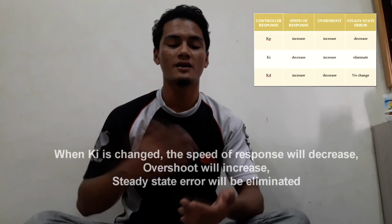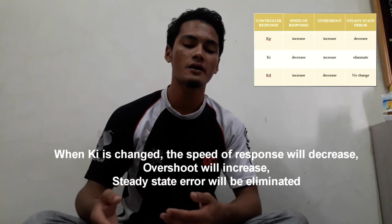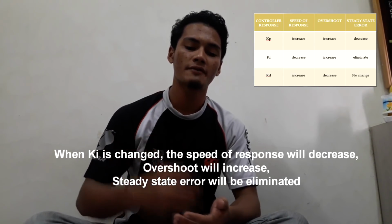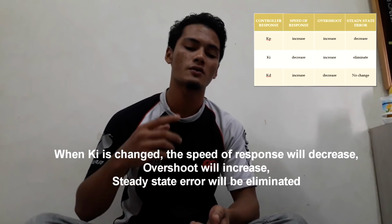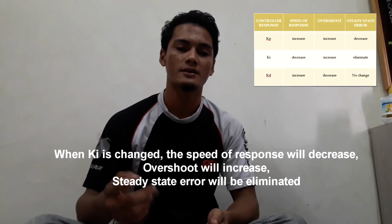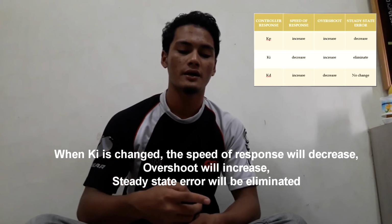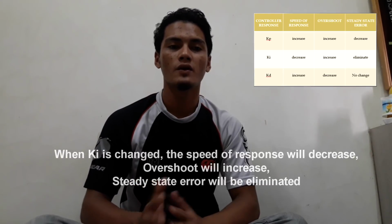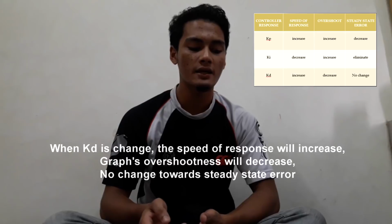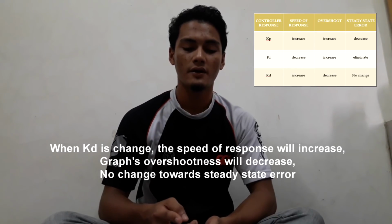Okay, second, when we change the value of KI, that is integral, the speed of response will be decreased. The graph overshoot also will be increased, same as KP, and the steady state error will be eliminated. Okay, the last one is KD for derivative.